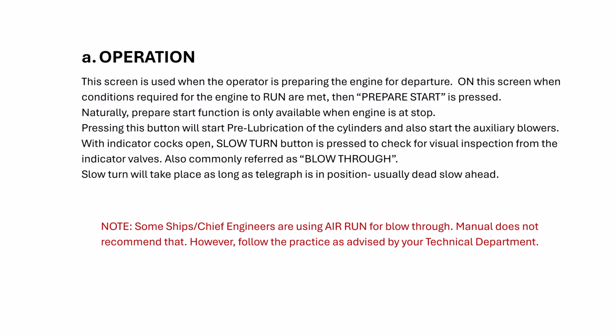Slow turn button, when you press, you can check for visual inspection from the indicator valve that nothing is coming out, no water or no oil if it were dripping. What we call commonly blow through. So this is the way we carry out blow through.